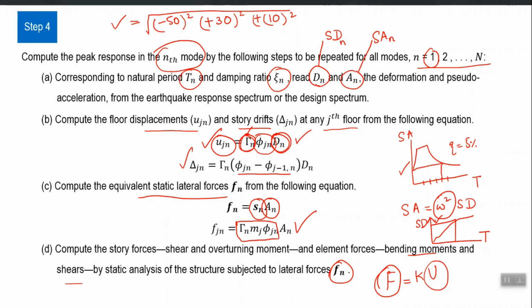So, even if in load combination you apply plus RSA and then minus RSA, even then the minus answer will be the most conservative number, and you will not be able to truly account for that effect which can be handled using dynamic analysis only.